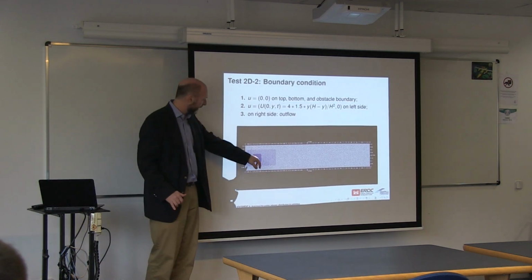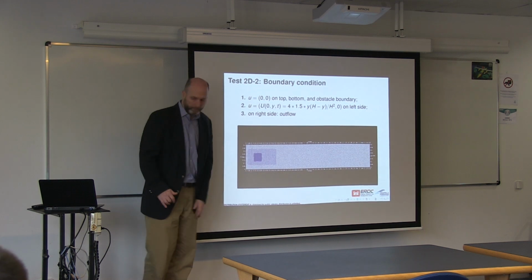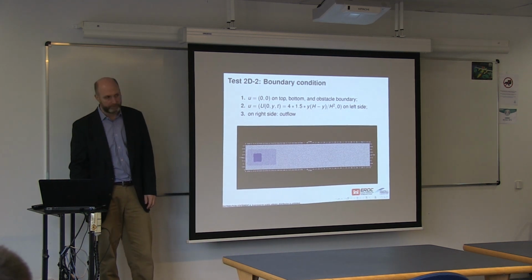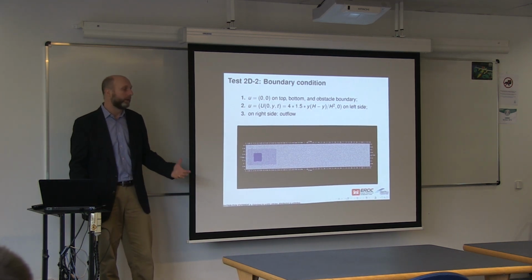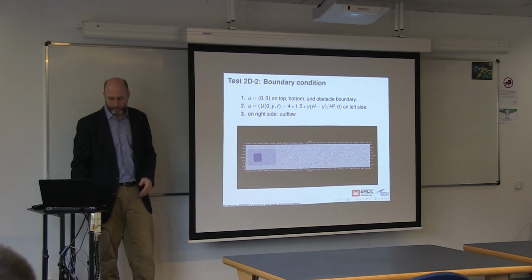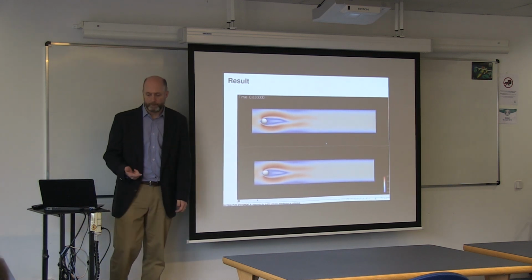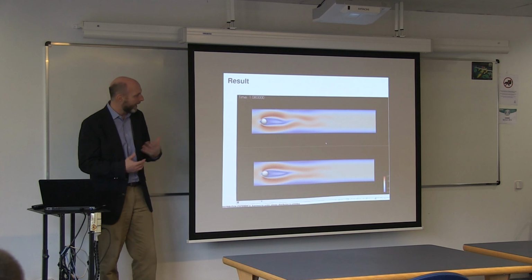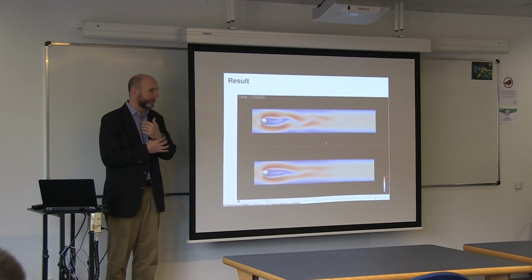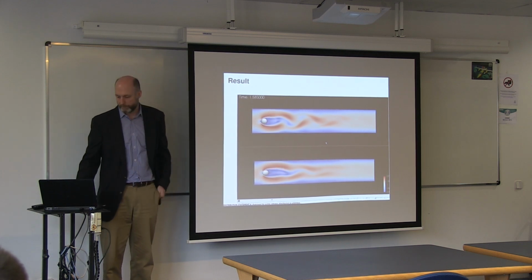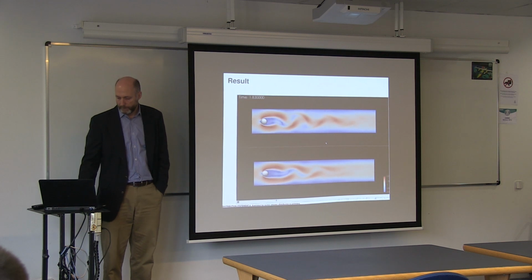And you see here, again, we have to actually do quite a bit of refinement near the solid surface that wouldn't be necessary, at least not as necessary with a fitted boundary method. So we're paying a price for our immersed boundary method. And so this is the comparison of the two. There's really, at this point, if we do sufficient refinement, to the eyeball, you get the same types of vortex shedding properties and the same types of boundary layers.